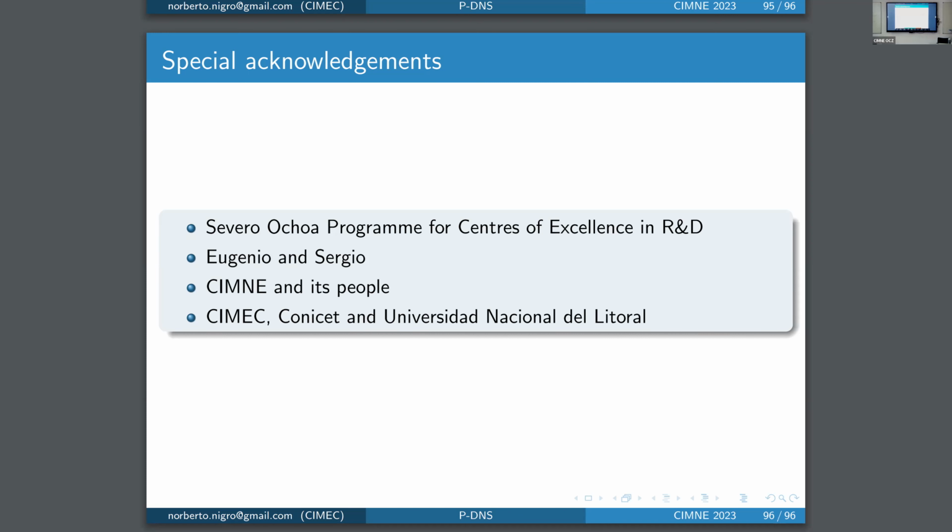The other thing is whether, with the same cost as an existing LES, you can improve results. This is possible. You mean energy range? If you do LES, you're cutting your calculation somewhere in the inertial range. Yeah, exactly. But the cost, when people claim that LES is very costly, is because the wave number where you want to cut your calculation is such that 1/the mesh size is that wave number, and that mesh size is very small. So you cannot get better than that. Another issue is that with the same cost as an existing LES, you get a better solution. But what you hardly will get is an improvement in the cost of LES. You understand what I mean? I don't know if my point is clear or not.